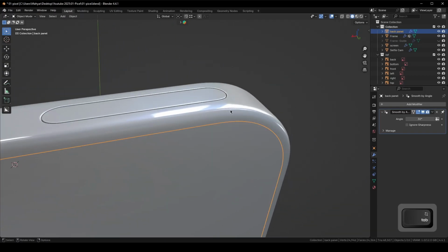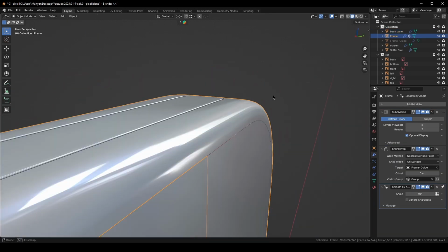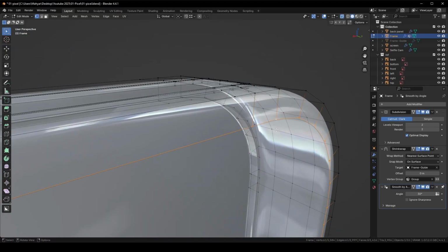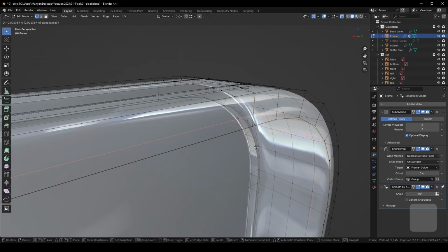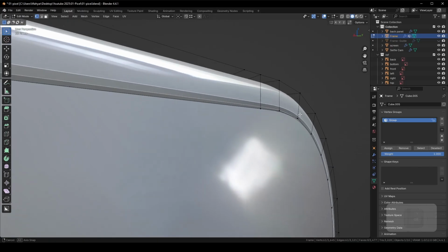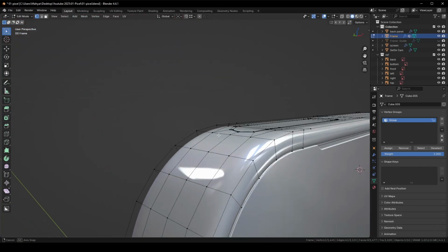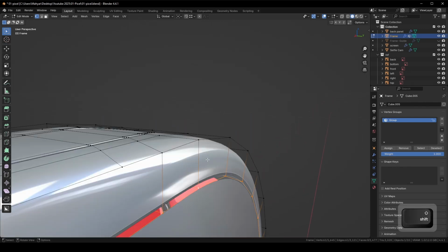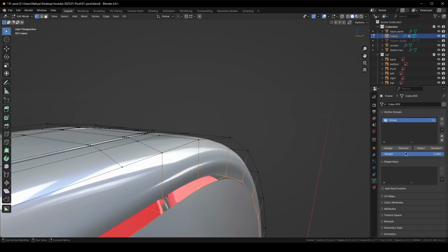Now I have to add an extrusion here, and I'm inside the frame. I want to remove this extruded vertices from the shrink wrap vertex group. Press Alt C to see the result. I also select this edge and remove this. Make weight 0.9 and assign it again.